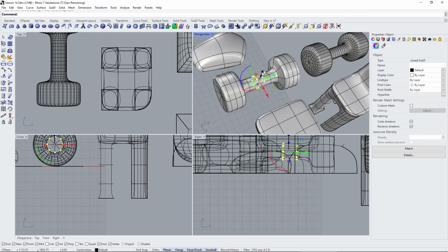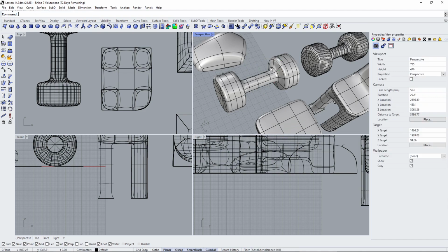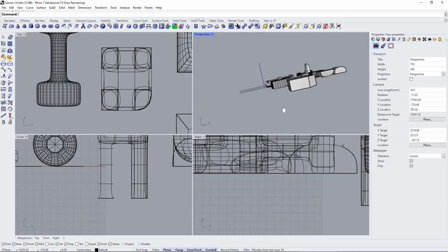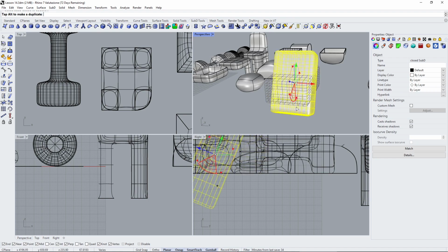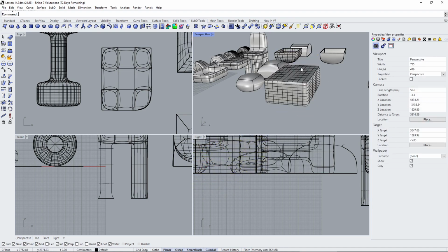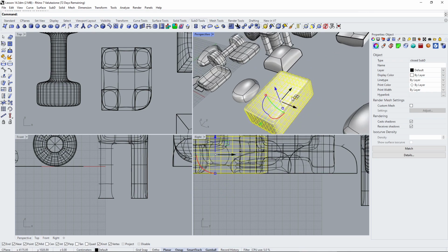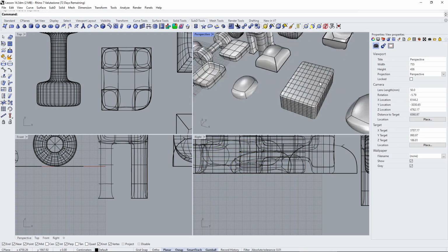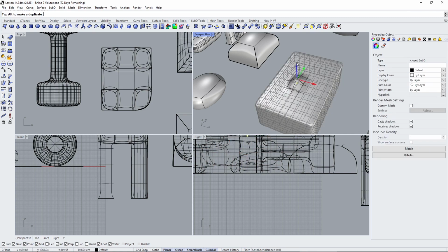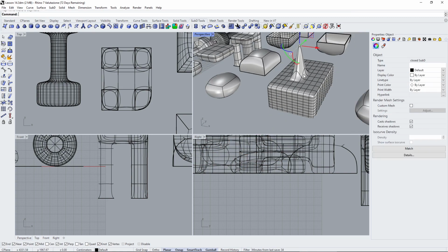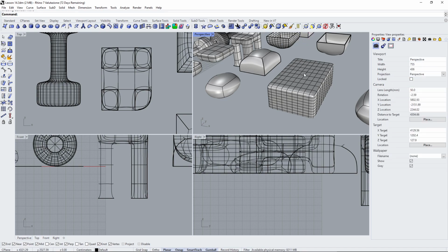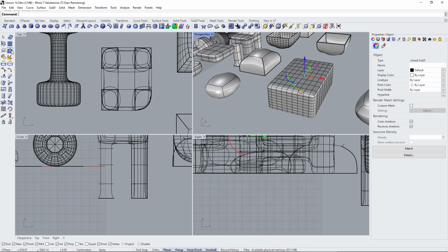can work with them. But when I have complex situations, for example, like this, now this is going to be more difficult to select all the points that I need or all the edges. So what I can do is use the soft selection basically. So let me see the difference. If I push this one up, this is going to be really concentrated. But if I select that point again and use the soft transform or soft selection, you can see I have a radius of selection.